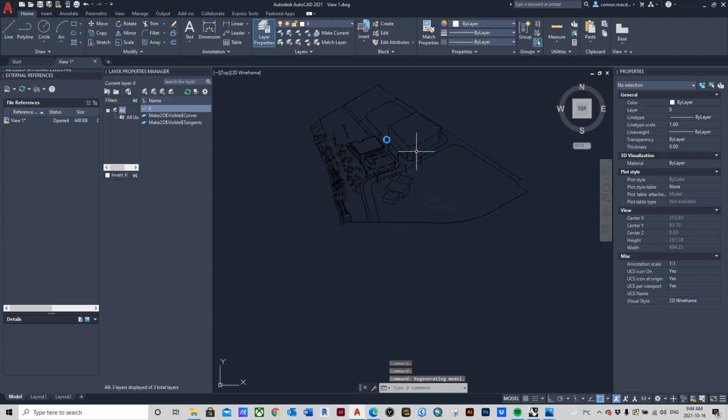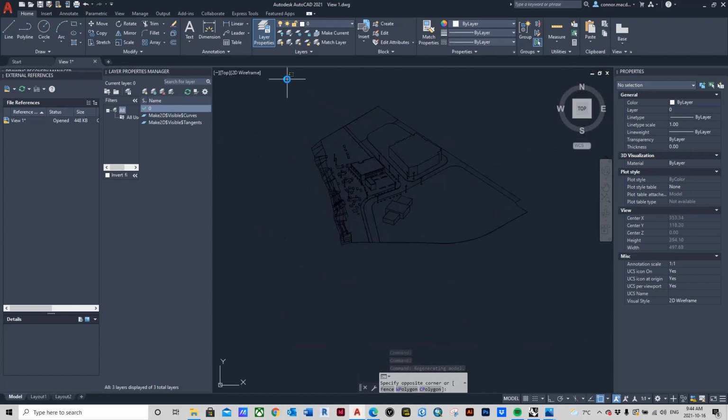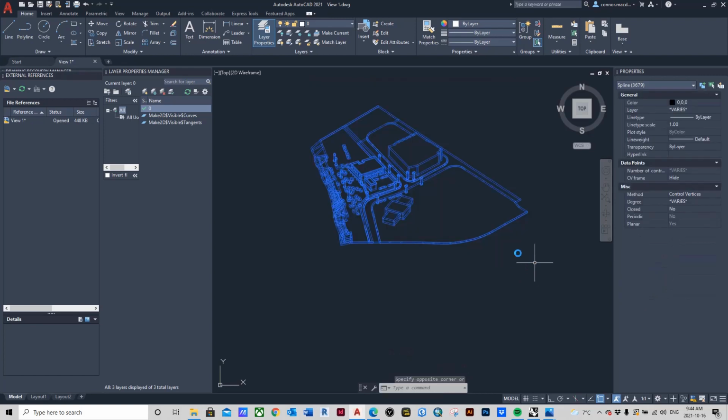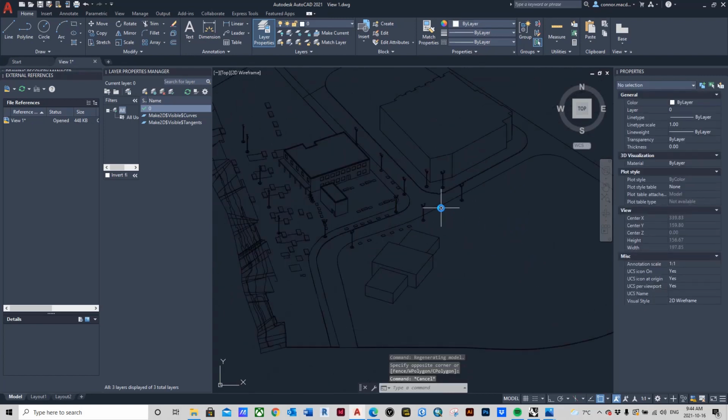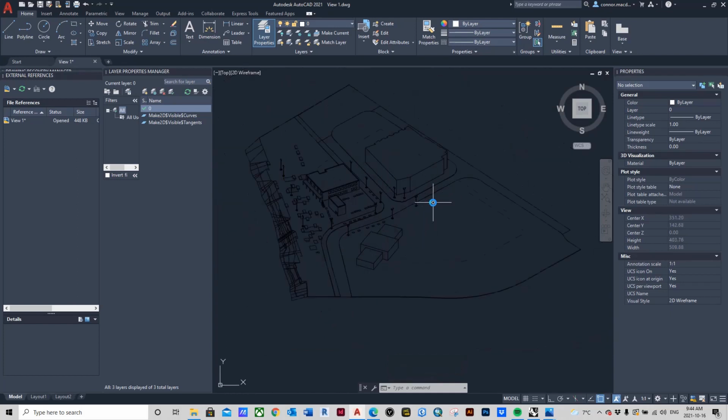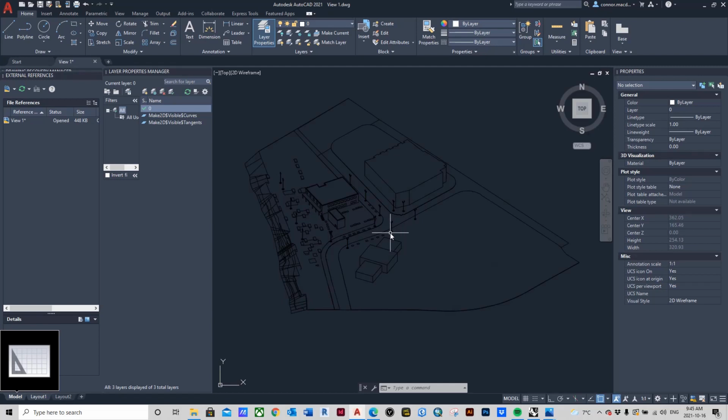Oh, I had to scroll out a little bit here, but as you can see, everything that we're looking for is now in the format of an AutoCAD file, which again means that if we want to, we could create a view for it, like I know you guys might have already covered at this point, and make this something that can be imported into Illustrator as a set of lines. But that's essentially the nuts and bolts of using the Make2D command. And this will be helpful in the next stage too when we're making axonometric and oblique views.